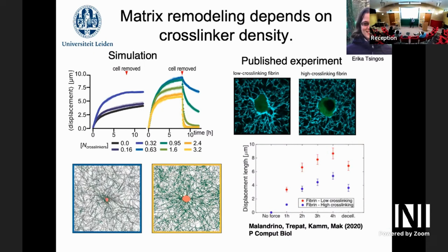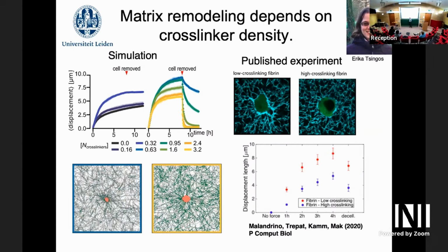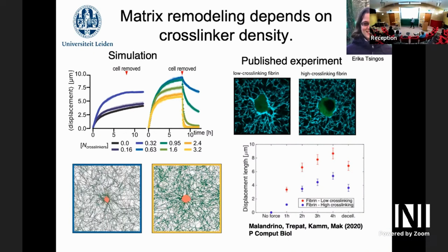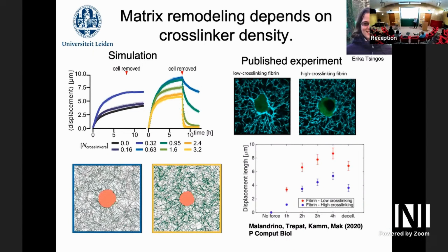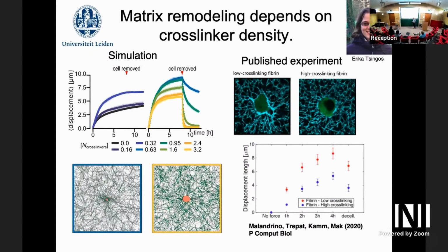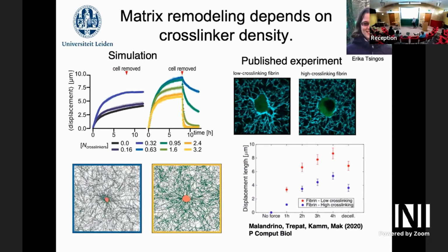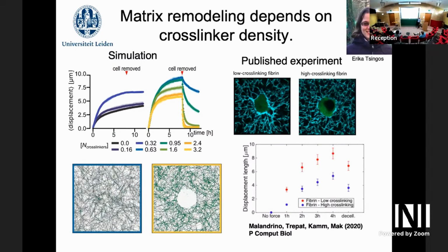And indeed, what you see is that it recovers completely, but with a little less percolation there's an intermediary stage where it recovers a little. But we don't have true viscoelastic behavior, only something like it due to sliding of some of the fibers. We don't have full viscoelastic behavior because for that we need dynamic binding and unbinding, which is work in progress.